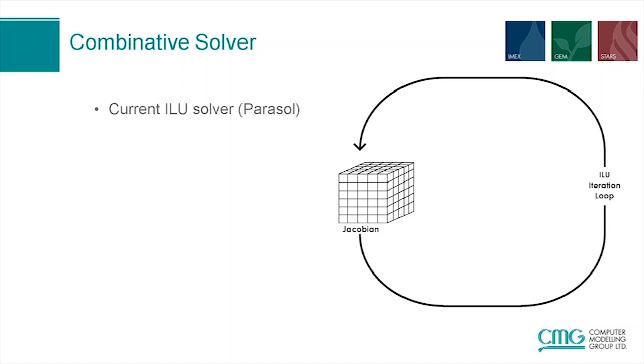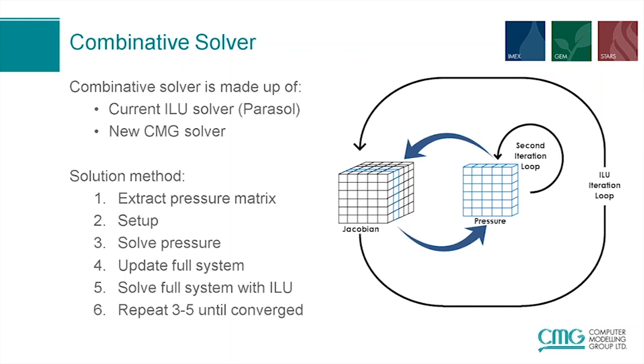Now, pressure is always a primary variable, so it's always being solved implicitly. So if pressure becomes an issue, this slows down this iteration loop. It takes longer to converge, and in turn takes more Newton iterations, and in turn negatively affects your time step control.